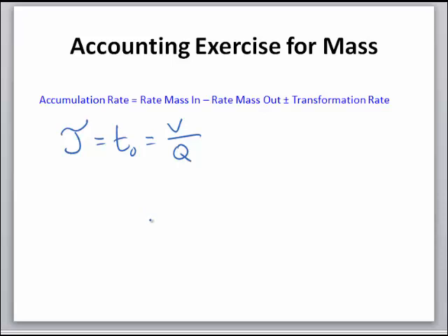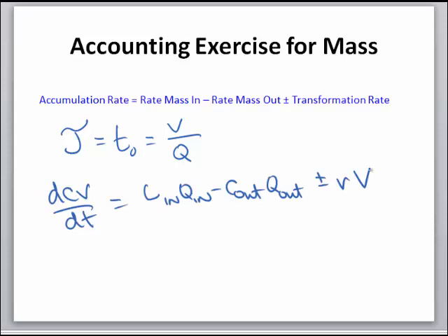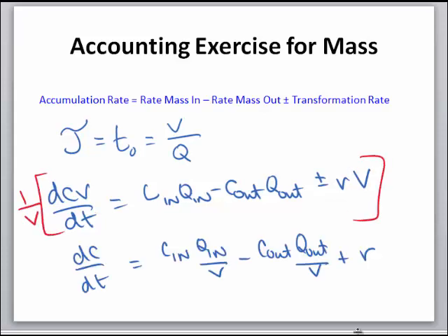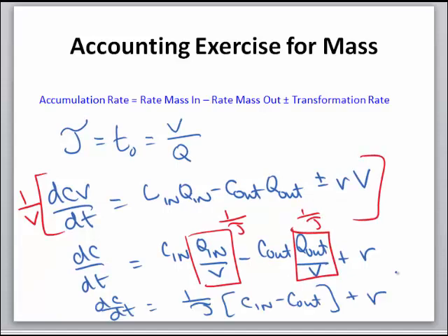The mass balance term can be rewritten to express hydraulic residence time. If you take this expression and you divide throughout by V, and you assume that the flow rate in equals the flow rate out such that those two terms are equal, you can write this in terms of tau. This term is equal to 1 over tau. This form of the mass balance is typical for a continuous flow system that is completely mixed.